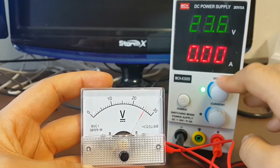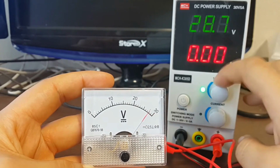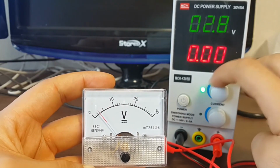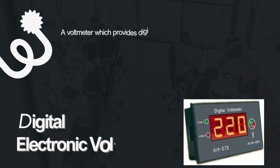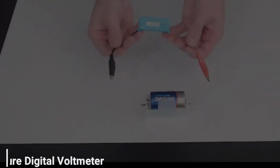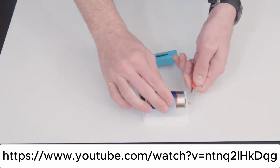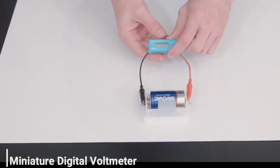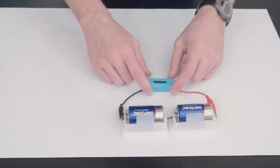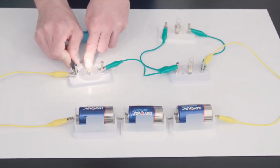Such a meter uses the electronic amplifier for controlling the input signals, and it is further classified into AC and DC analog electronic voltmeter. Digital electronic voltmeter. A voltmeter which provides digital output reading of the measured voltage is known as a digital electronic voltmeter. The output of such a voltmeter is in the form of a numerical value. Digital electronic instrument reduces both the human and the parallax error because the reading is directly shown in numerical form.